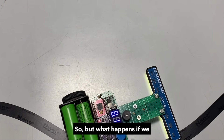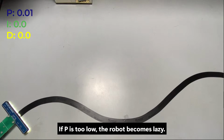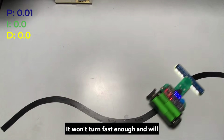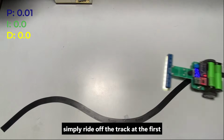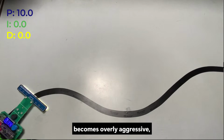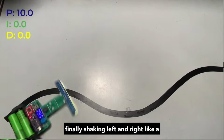But what happens if we tune these values incorrectly? If P is too low, the robot becomes lazy. It won't turn fast enough and will simply fly off the track at the first sharp corner. If P is too high, it becomes overly aggressive, jerking left and right like a snake.